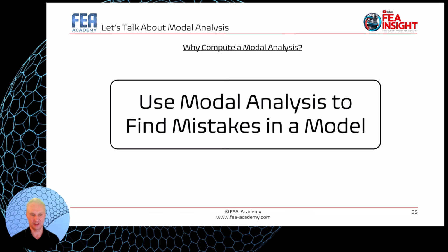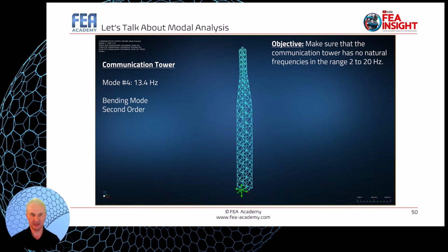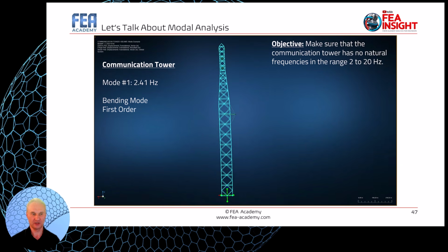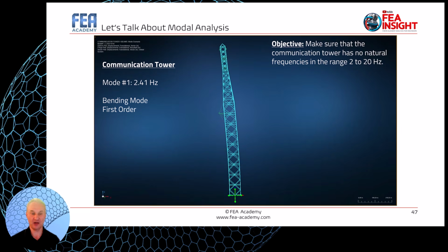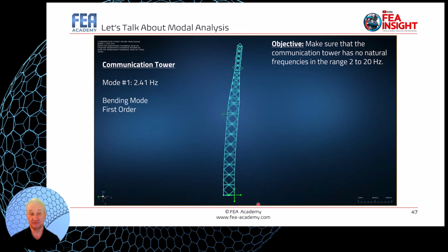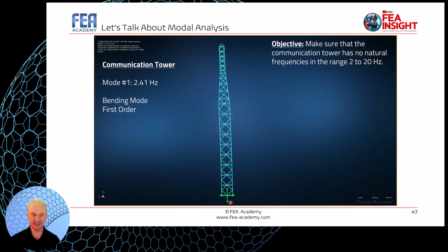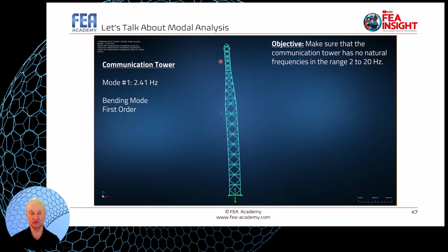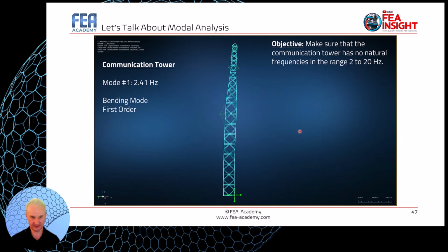So, sorry, if I come back here, you see, if I go back to the first mode, I need to solve the bending mode. So I have many choices. I can increase the base of the tower to solve this problem, or I can even use some reinforcement going like that and like that in order to stabilize those modes.